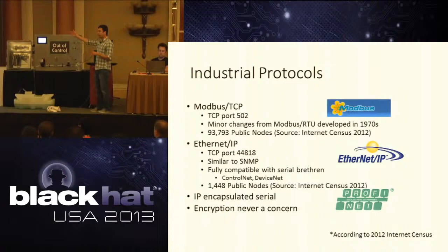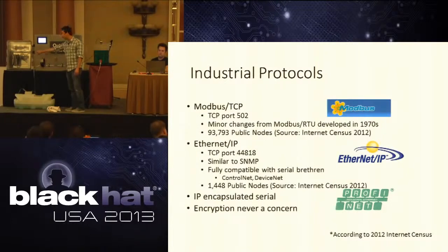We have a couple other protocols that are open and used pretty widely. EtherNet/IP is one, Profinet is one. But, like I said, there's an obvious reason why we chose Modbus TCP, and it's up there. Because there are 93,000 nodes on the internet, from the Internet Census of 2012, that are listening on TCP port 502. It may not necessarily be an RTU or a PLC. It might be one of these guys, but Modbus is used to control processes out in the field.